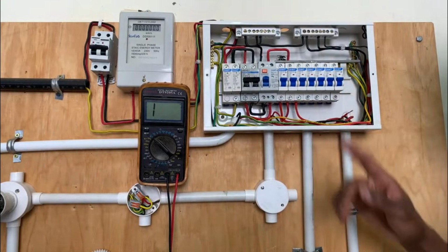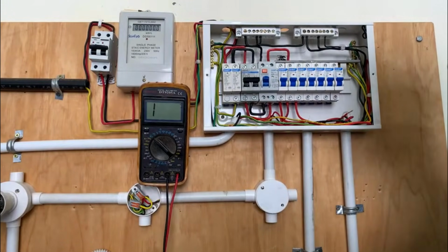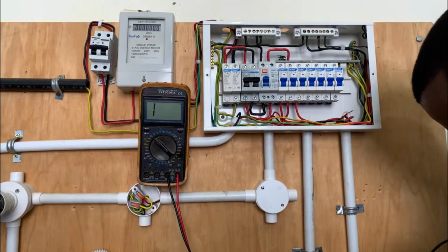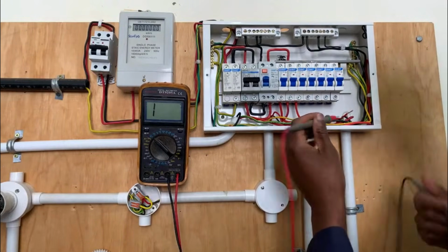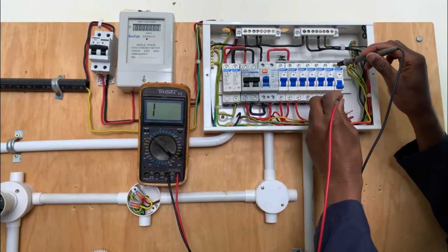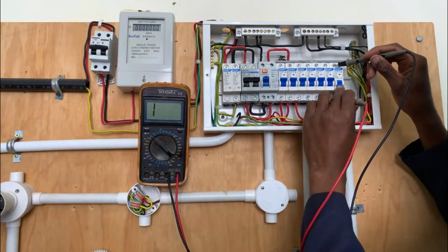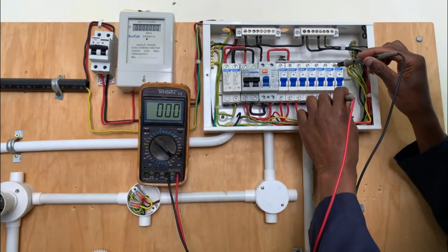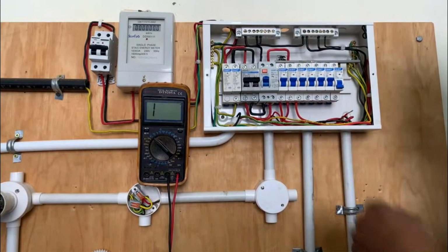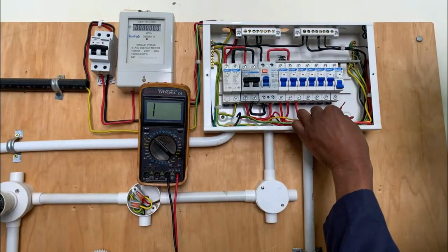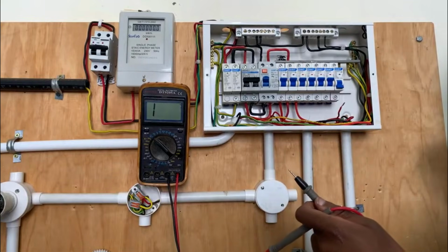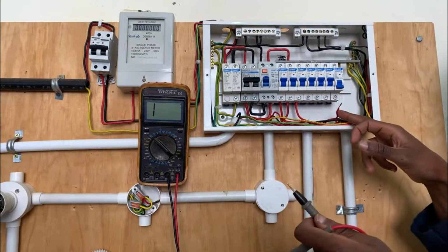So we have isolated it and we can confirm that indeed it is electrically sound because of that beep. Now, what we need to determine is, if you shut it off and place the probes, you get a 1, infinity. If you turn it back on, there is a short circuit, meaning continuity. But we shall not reconnect this circuit back until we solve the problem. Continuity means a short circuit, and we do not expect a short circuit between this line and the neutral.